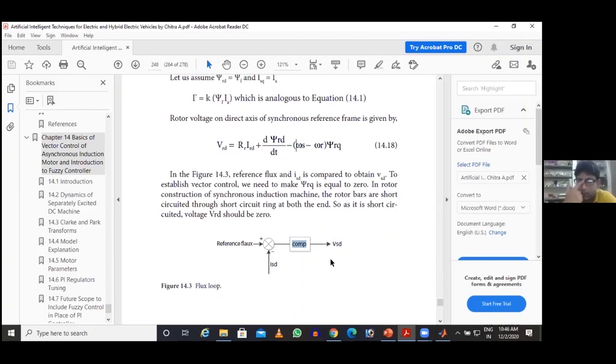One day I will tell you some simple technique how to tune that, because in this control there will be a total of three PI regulators. Why PI? Because it's a first order system. PID is second order, so unnecessarily the higher order effect will come to increase the transient. And PI regulator implementation is also much easier. That's why most of the industry will use PI, where robust dynamic response is required.